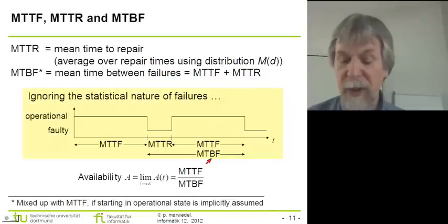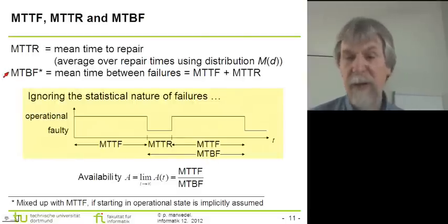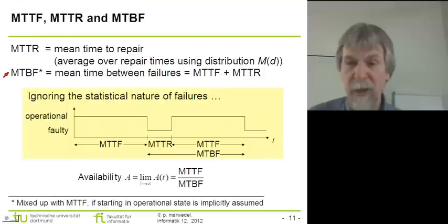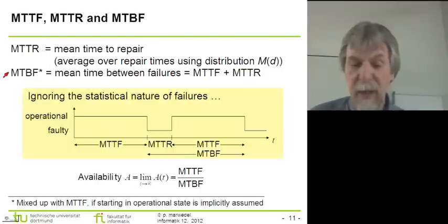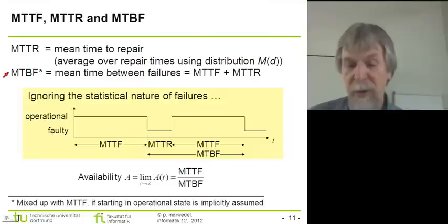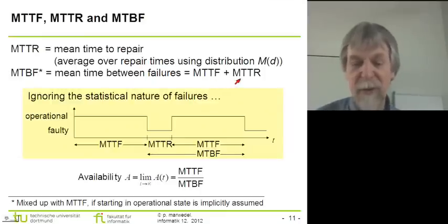Unfortunately, there are many cases where MTTF and MTBF are mixed up, because if you look, for example, at the specification of a hard disk, you will frequently find values cited in terms of MTBF. This, strictly speaking, is totally wrong, because if your hard disk breaks, you will just throw it away. You never consider the repair. So talking about the time for a repair is totally useless in this context.